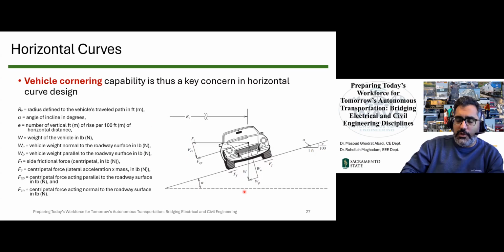And it's very important to make sure that there is a balance here. As the vehicle is moving, this shouldn't be too high to drag the vehicle inside, or the vehicle to be thrown away out of the curve, or even if it's a slippery road or icy road, the vehicle could slip downward. So it is important to make sure that there is a balance here.